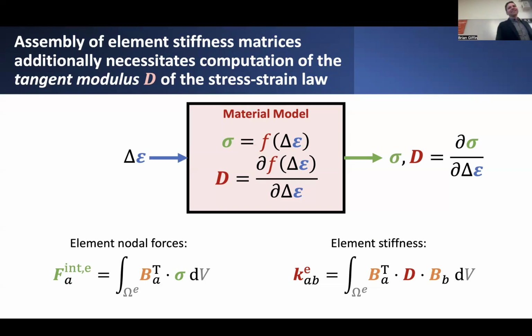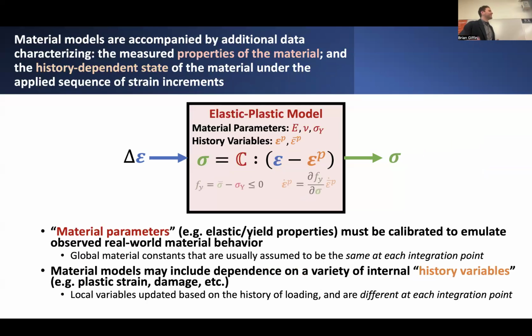So you can think of it as basically the tangent stiffness of the material. It's sometimes called the tangent modulus operator, but basically it is nothing more than the derivative of the stress components with respect to the incoming strain components. Okay, that's all you really need to do.